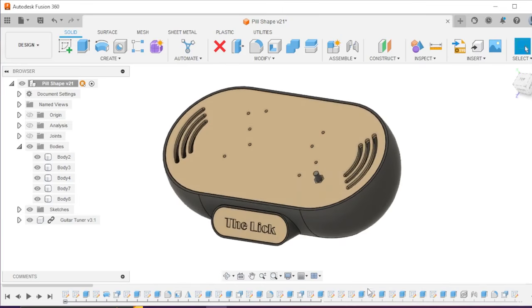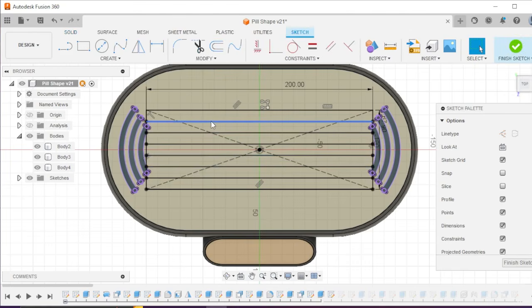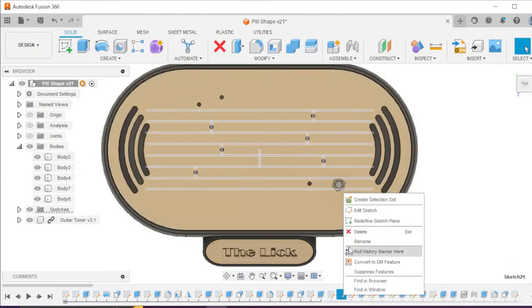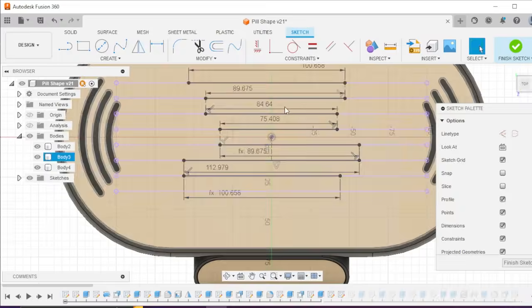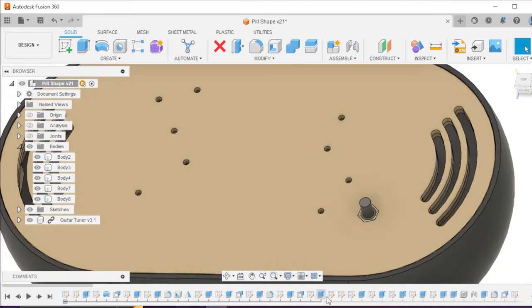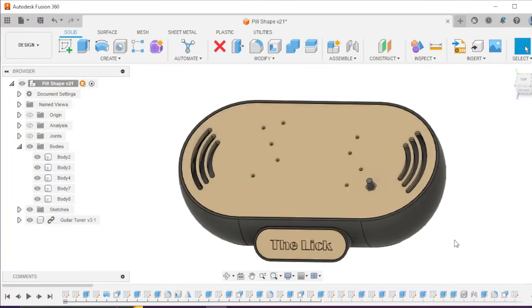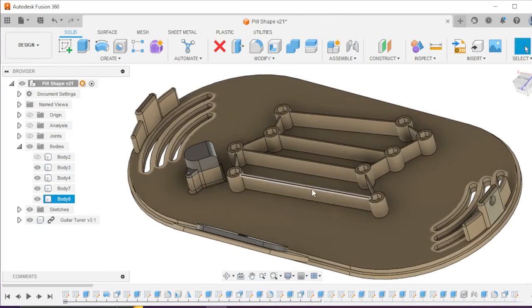The details of how these lengths get turned into a Strumley soundboard is something that we do in CAD. The note spacing is set by the V-groove bearings I'm using to wrap the string around. I then put the string lengths into the sketch and draw some supporting bosses to resist the tension of the strings. Once tuned up, the strings will produce somewhere around 80 pounds of tension, trying to rip this print apart, so any and all bracing we can provide will be helpful. And to terminate the string, I'll use a sacrificial bearing to loop it all around.